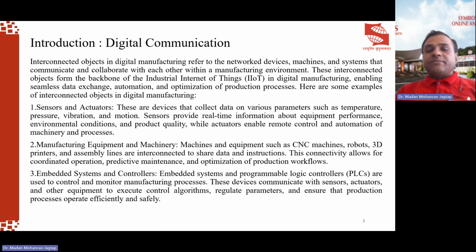Embedded systems, we can say electronic systems, have sensors connected with them. And with programmable logic controllers, PLCs, as we know, we can write a program on the PLC, so that it can be executed through the actuators on a real-time basis, and it will perform some activity in the manufacturing environment. So the programmable logic controllers are used to control and monitor the manufacturing processes.